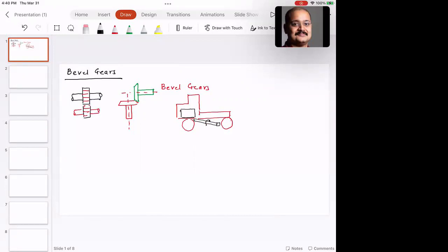The only additional step is that a knuckle joint is not expected to perform under fatigue loading or continuous operation. On the other hand, a universal joint is expected to withstand dynamic load. So just like gear trains, you will have to look at the dynamic load and the wear load, but the concept for design of a universal joint is similar to the design principles that we have been studying so far.